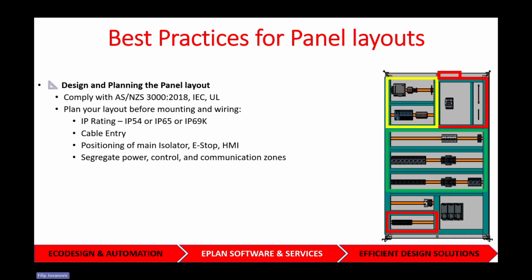Another good consideration is to segregate your power and control, because high power devices, especially like VSDs or even just power cables, will emit EMI, and you don't want that EMI to have any impact on your control circuits or control wires.